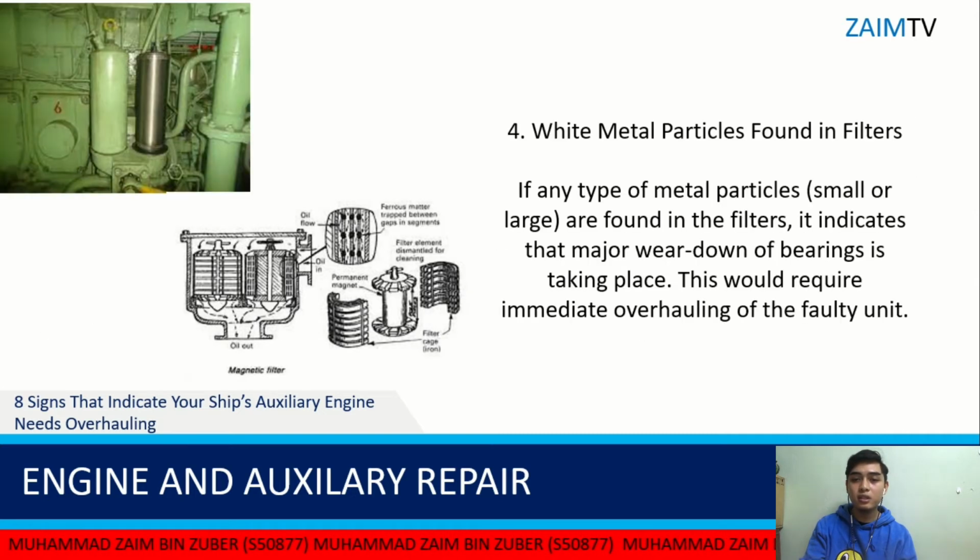The fourth sign is white metal particles found in filters. If any type of metal particles, small or large, are found in the filters, it indicates the major wear down of bearing is taking place. This would require immediate overhaul of the faulty unit.